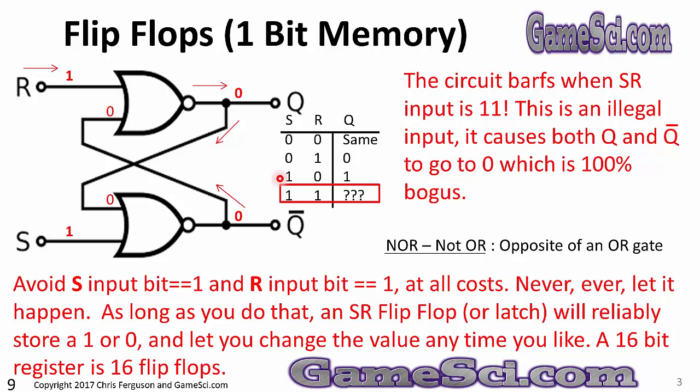Set the S input to 1 when you want to store a 1 in this flip-flop. Set the R input to 1 when you want to store a 0 in this flip-flop. And maintain zeros on the input when you want it to hold a bit of computer memory.